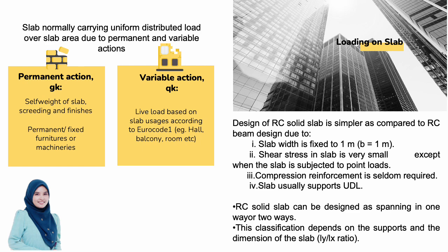Number three, less compression reinforcement. Unlike beams, where compression reinforcement, such as stirrups or ties, is often required to resist the shear and provide ductility, solid slabs generally require less or no compression reinforcement. This simplifies the detailing and the design of the slab.